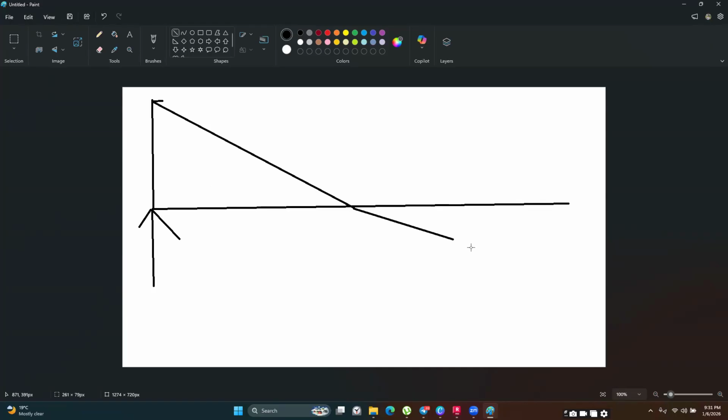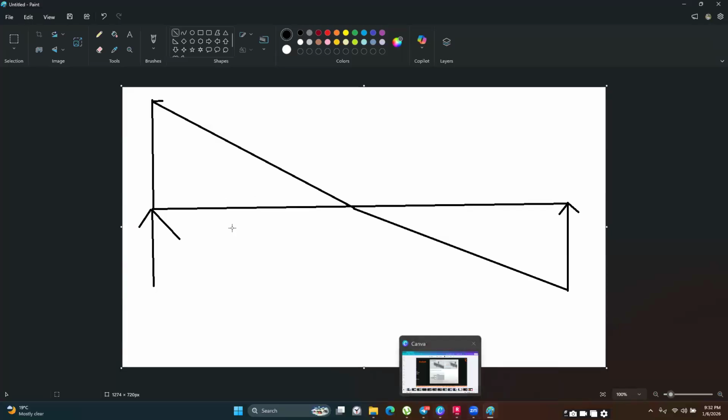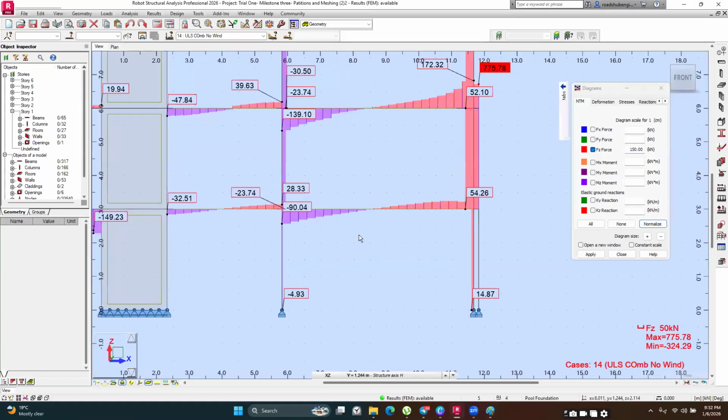And then once you get to the 0 point here, it is going to continue decreasing because these loads are increasing. And then at this particular point, you have another reaction that is going to be bringing it back to 0. And this is what you would expect to have for your shear force diagrams, especially for beams that are supported on both ends. Okay, so when you come here, this is what you expect.